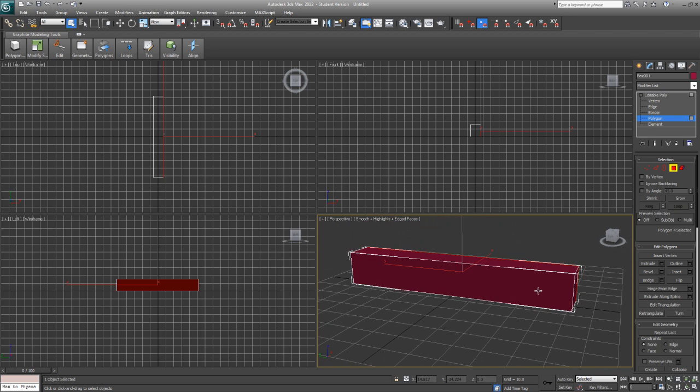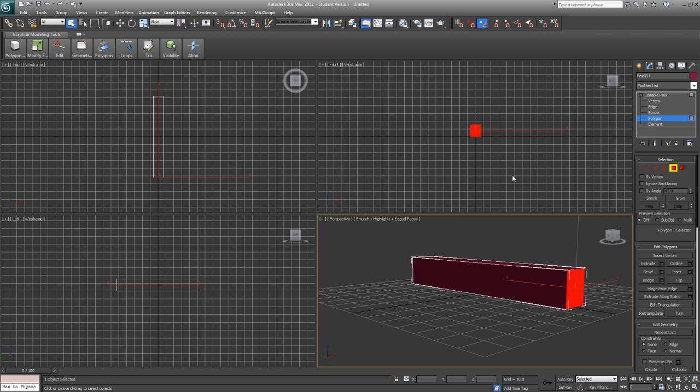Okay, so basically what we want to do is taper the rear, which would be here, the back of the model. And you can see that's selected here in this view. The back of this is being selected. Then now we can finally direct ourselves up here to the top. These three icons are the most important thing that you use in this top toolbar. First one is to just move the box around or to move the sub-object around, which in this case would be the face.